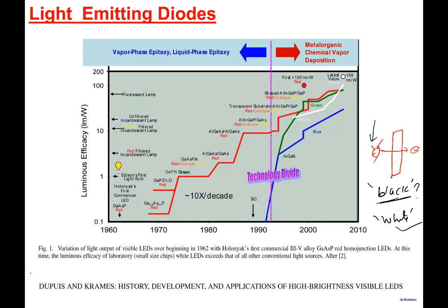Even if you have a red LED, a green LED, and a blue LED, let's say you have all these LEDs available, the trouble is, red LEDs, as you can realize, will require a different band gap. Green LED for emission will require a different band gap. Blue LED will require a different band gap, meaning 3 different semiconductors. 3 different semiconductors in general means all these semiconductors are crystalline, which in general means 3 different lattice constants. Now, to make a display, you need red, green, and blue. How do you make red, green, and blue on the same substrate?